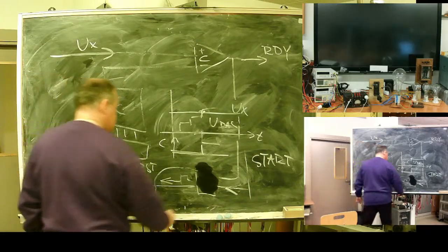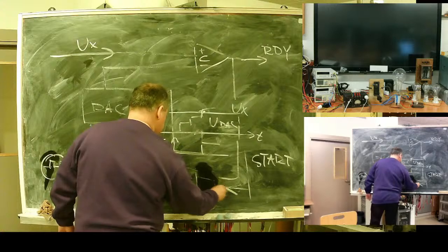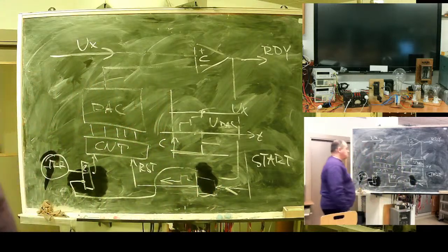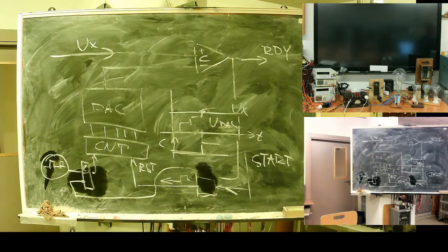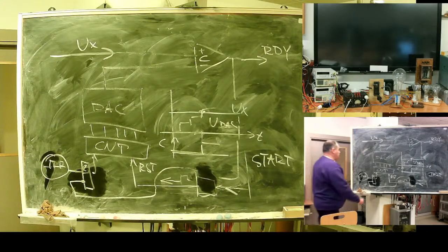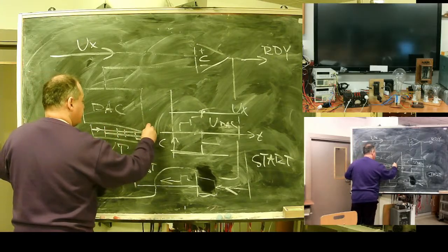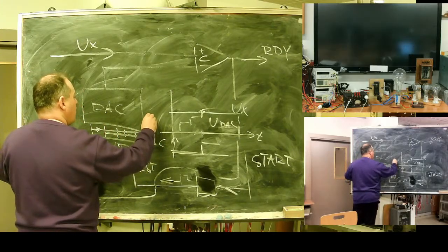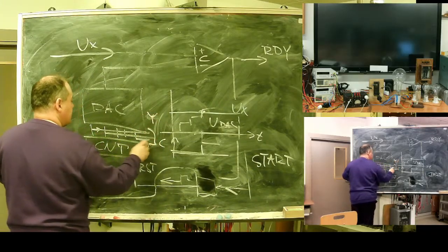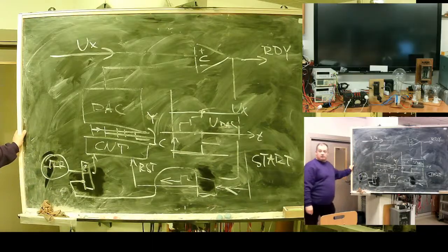I don't need to block the start signal. I need to block the clock signal. That's how it works. So at this point the clock will be stopped, the counter frozen, and when the ready signal arrives, our Y can be taken as the content of the counter. Understood?